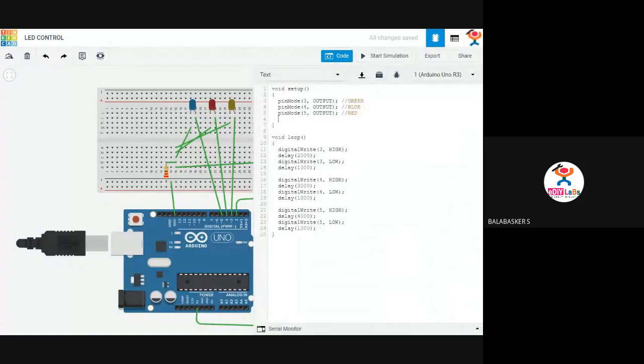I'm going to add another one, that is for reading that switch, pin mode. I have connected that pin to the second pin. So the second pin is my input pin. Input is nothing but from where that input is taken. So from here that value will be read by this controller. Here I have to add another two lines. Int button. I have declared a variable called button. It is an integer value. I'm going to read that value, digital value, digitalRead of my pin number 2.